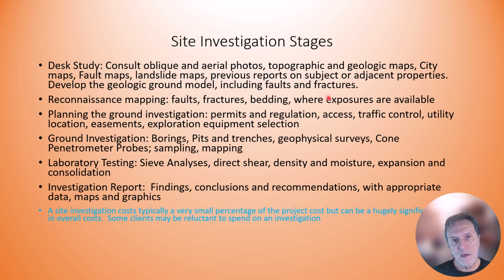So with all that done, we can figure out, well, what kind of equipment can we get in there? Can we get a drill rig, truck-mounted drill rig in there? Can we get a backhoe in there? Can we get a portable tripod type rig that can be carried in by a few men? Can we dig manual hand pits? Will that give us our information? Okay. Then we actually do the ground investigation.